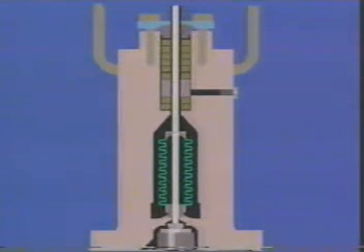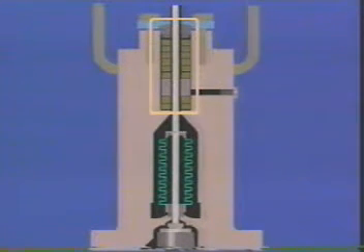The material and construction of a bellows limits its use to relatively low-pressure, low-temperature applications. Also, the life cycle of the bellows is unpredictable. Because a failure of the bellows could be catastrophic, this design normally includes a backup packing box. A double packing seal is often used in highly toxic applications.